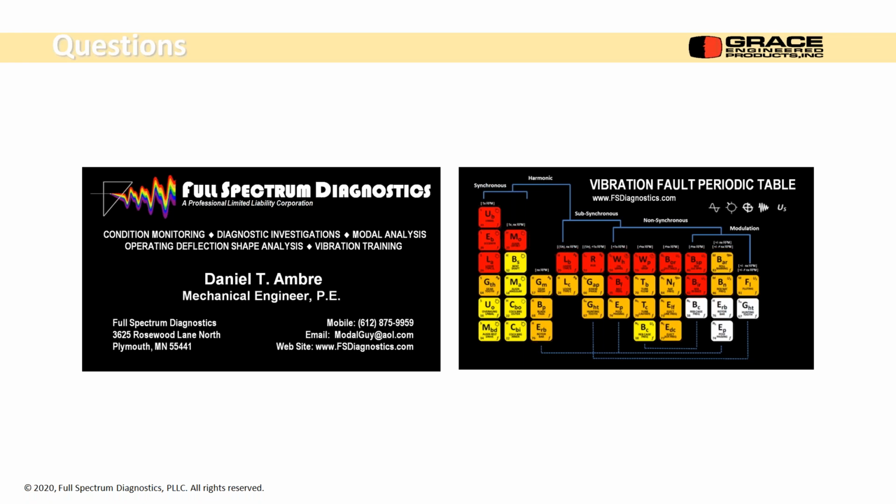All right. Next one: what is the difference in vibration reading using a portable on top of the bearing housing versus the probes? Versus the proximity probes, I assume you're saying. If you have a transducer on top of the housing, you're measuring the housing vibration. If you have proximity probes, they're designed to be installed through the bearing and within 50 mils maybe of the shaft. So they put out a magnetic flux that can vary with the distance in that gap.